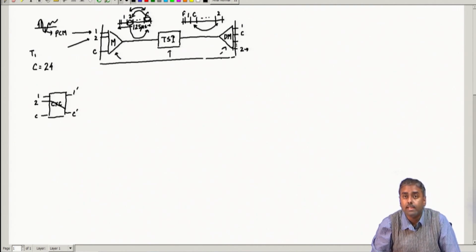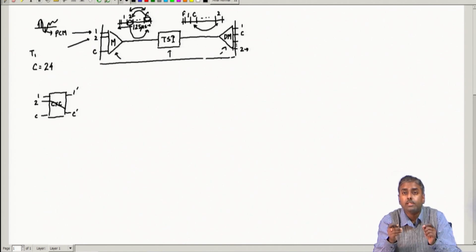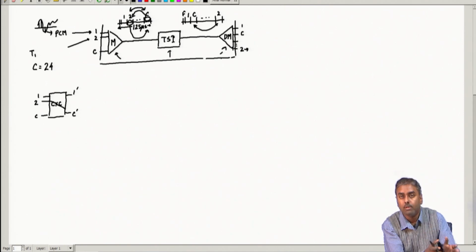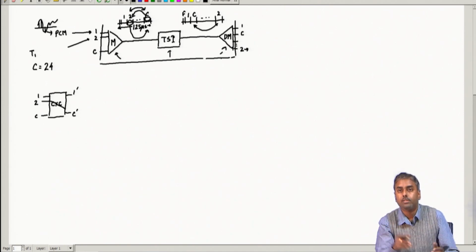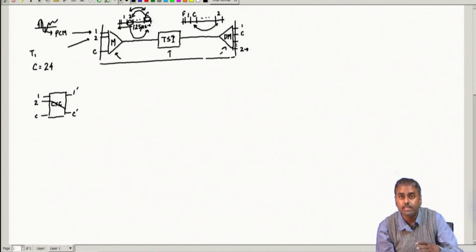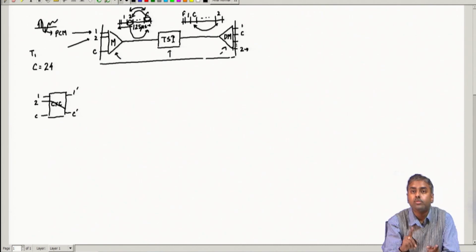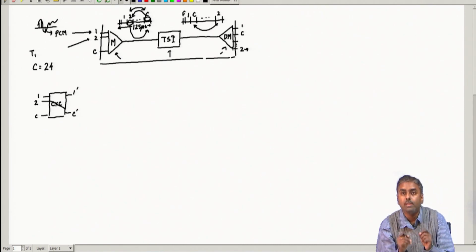Okay. So, this is another dimension of switching. You will see that for this switching you do not require a spatial port or any spatial switch matrix. Over here all you have to do is logically swap the location of the bits or bytes, let us say, in the sequence of the frame. Whichever sequence they are in the frame, you just swap that. So, basically what you do is, every frame you will be swapping these things. That is the logic you will have to keep.